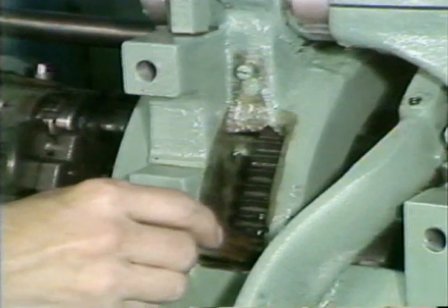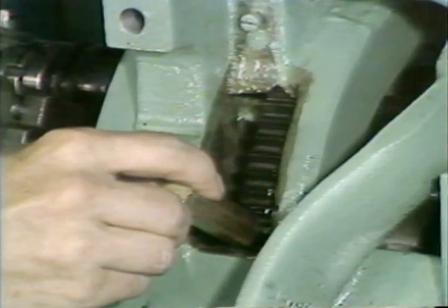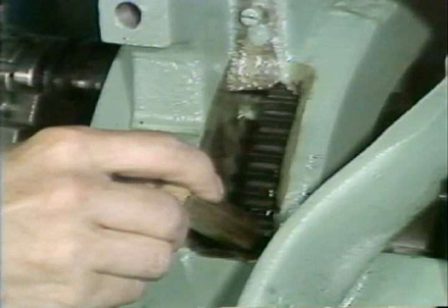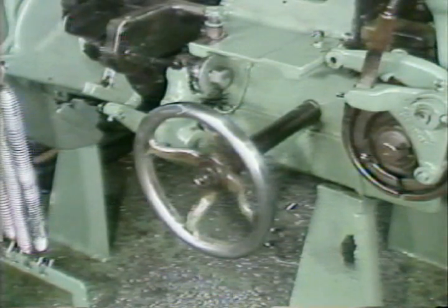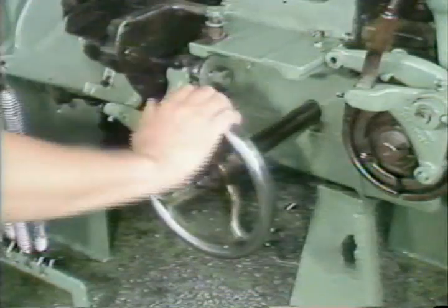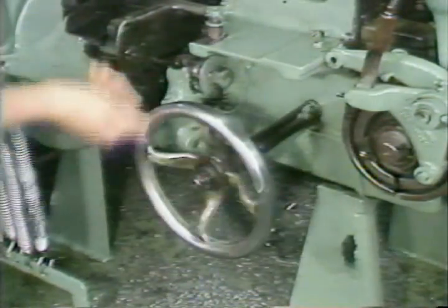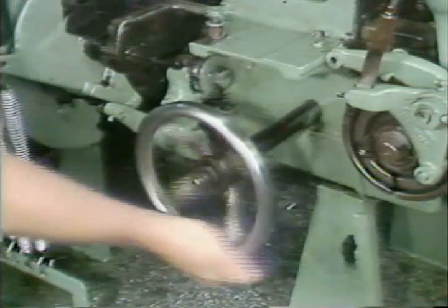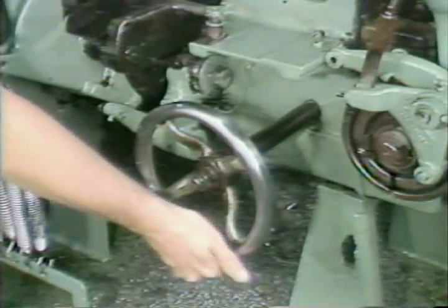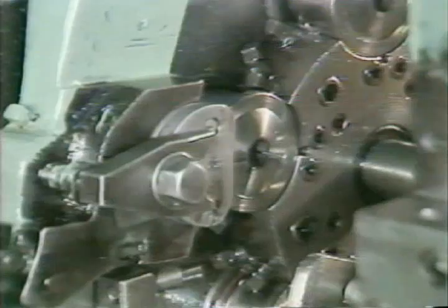Screw the collet into the inner spindle. Tighten the collet with the brass bar placed to keep the spindle gear from turning. Once it is tight, you can remove the wrench and the brass bar. Whenever the collet is replaced, the collet tension must be checked and adjusted if necessary. To do this, hand crank the machine forward to the completion of index. Place a bar end in the collet.